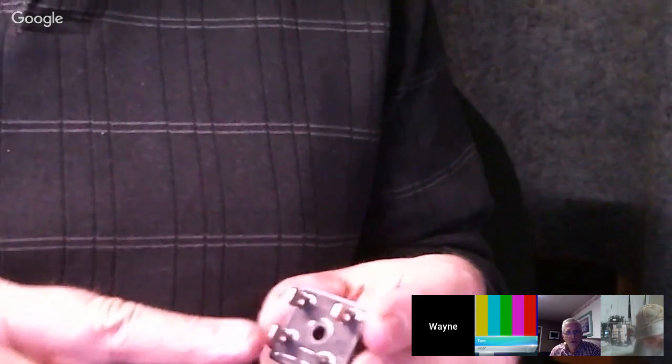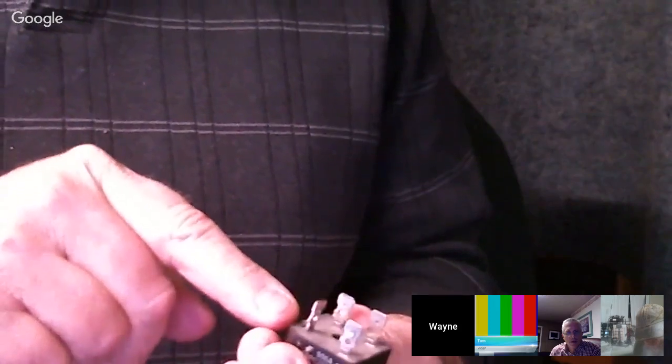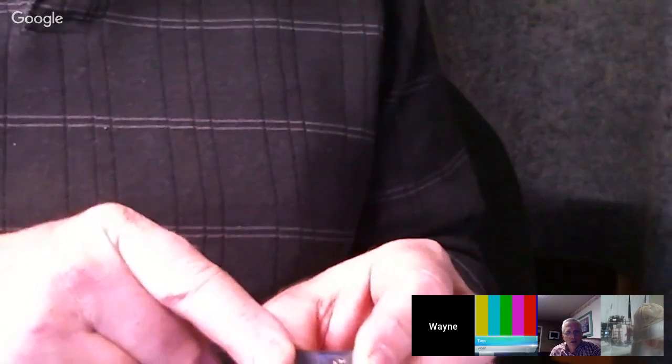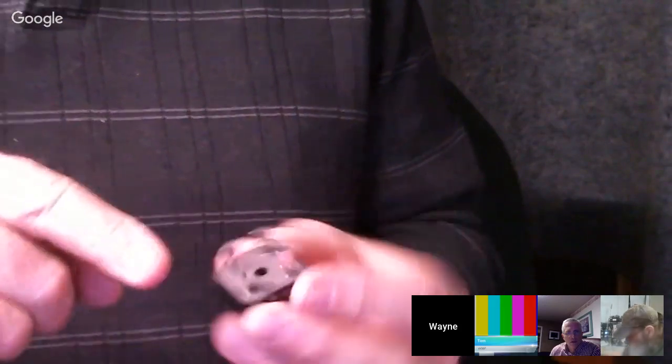When it's positive, it feeds out on the positive side. When it goes negative, it goes to the negative side of the rectifier. That's what turns it into a direct current feed, changes AC to DC. I want to make this as simplified as possible. Let me go over here to this other site.